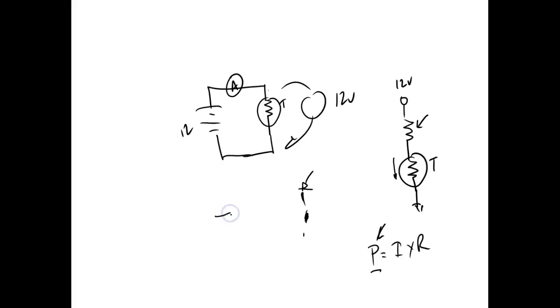Another way we can do it is send it through a Venturi, which is just a compression, and then we put a pressure sensor right here, and then we put a pressure sensor right there. Of course, the faster it flows through that, it creates low pressure, just like airplanes fly, you know. So you'd have a high pressure side here, you'd have a low pressure side right there. And the difference between those pressures would be proportional to the what? To the flow. So there's several ways we can measure.